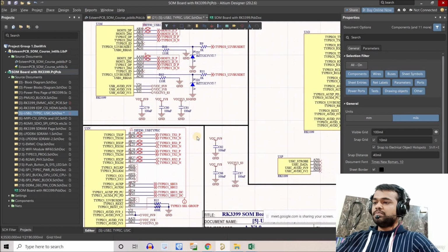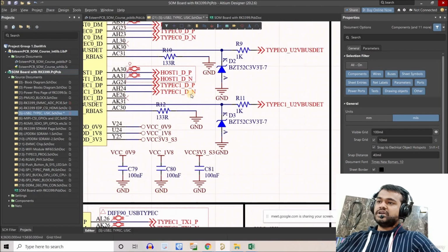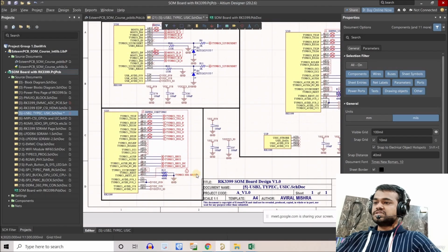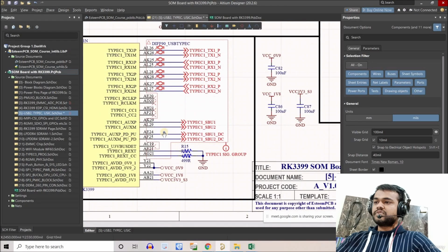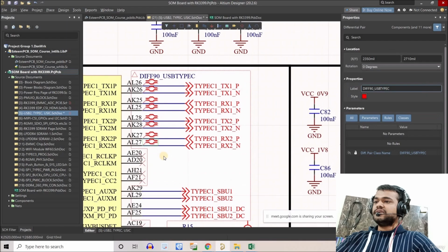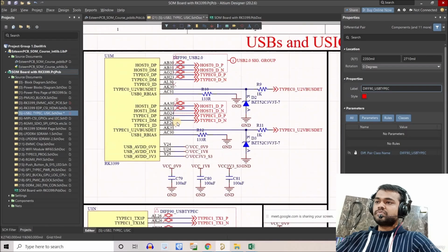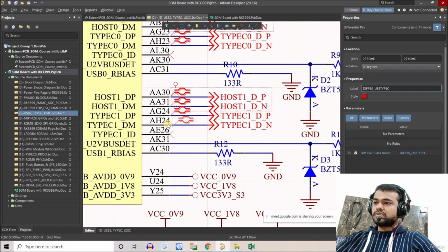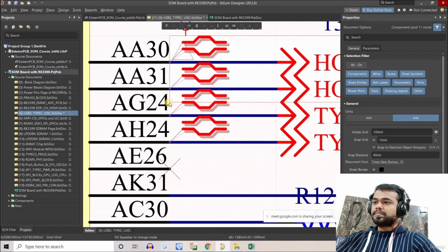Okay, here I made one more mistake. I forgot to include these Type C data plus and data minus connections with the signal group of this, and these are again differential. So what I will do, I'll just copy one of these. Firstly, double click on this, so you can see it is differential 90 ohm USB Type C, right? And the same impedance is for the other differentials as well here. So firstly place those, and then we will place the blanket as well.